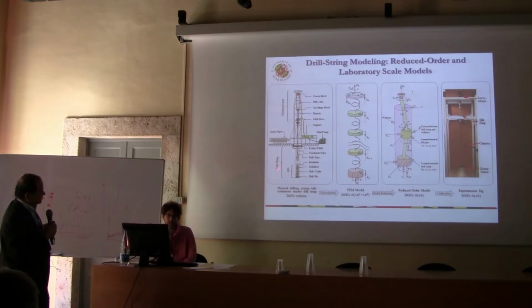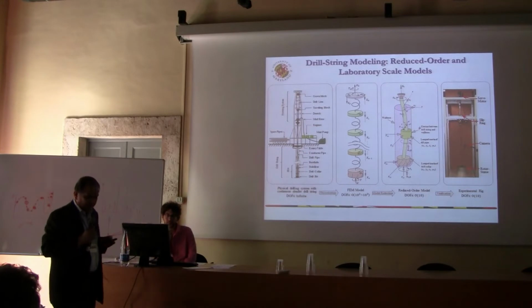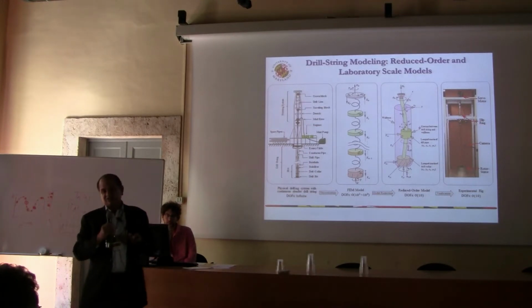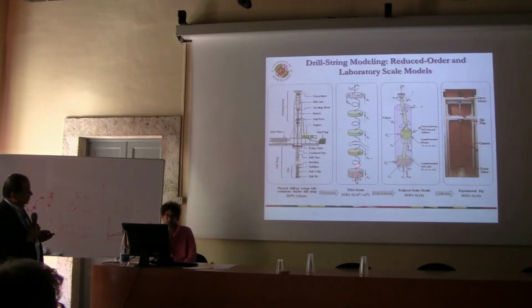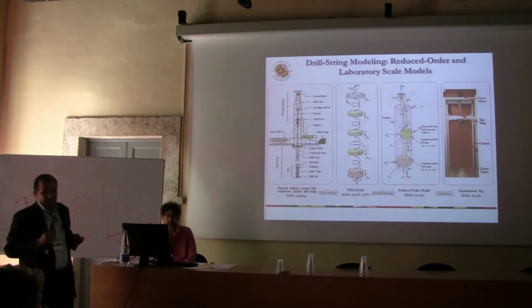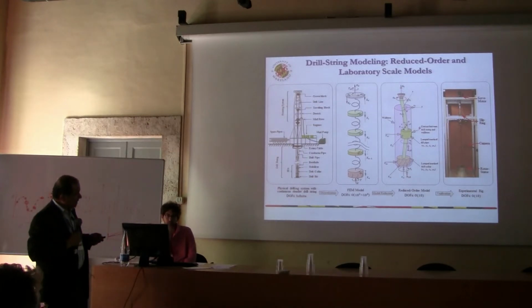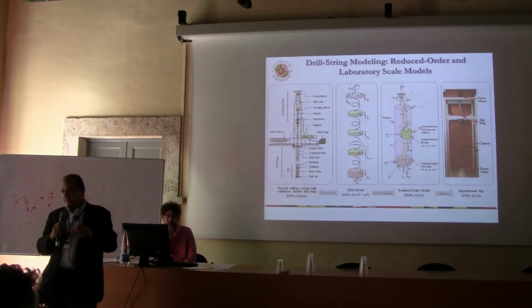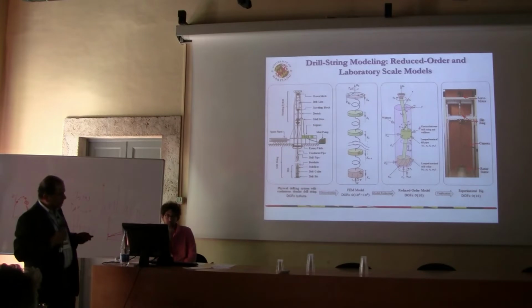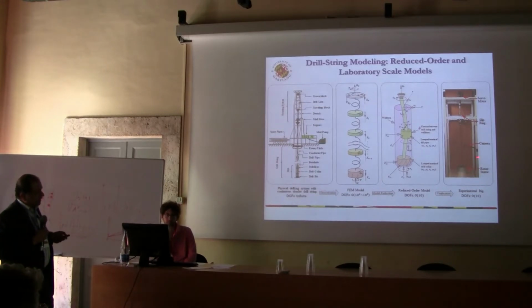So to study the dynamics of the system, if you were to write the partial differential equations out, that include the time delays and everything, it's an infinite dimensional system. So one reduction that one could do, this is the spatial dynamics, you could discretize the system and end up with a finite element model, where the degrees of freedom could be 100 to 1,000 if you wish. And if you want to isolate the physics, for instance, if you'd just like to understand what happens between the stabilizers and the bottom hole assembly, you could come down to a model which is of 10 degrees of freedom.